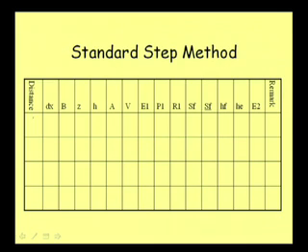Distance means, say our starting point is 0 and then we are continuously computing the profile. Say the first distance is 50, the second distance may be 100, increasing by 50, but for the next distance there is no restriction. Suppose we take 200, then there is a gap of 100 between, and here is a gap of 50, here also a gap of 50. It does not matter.